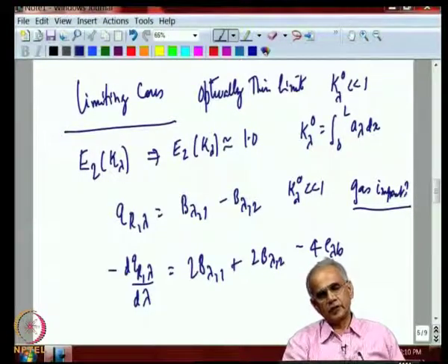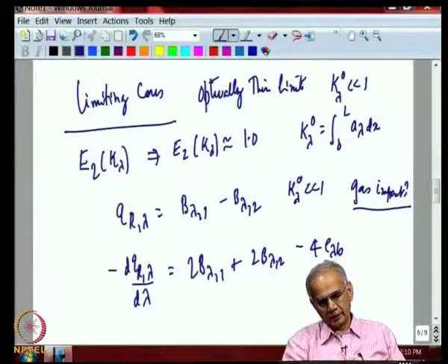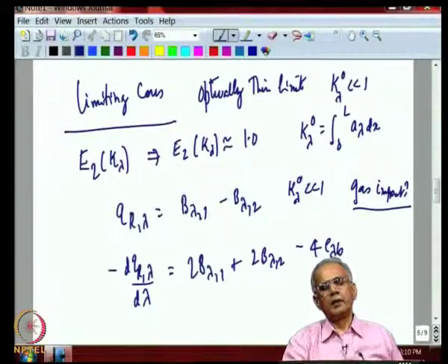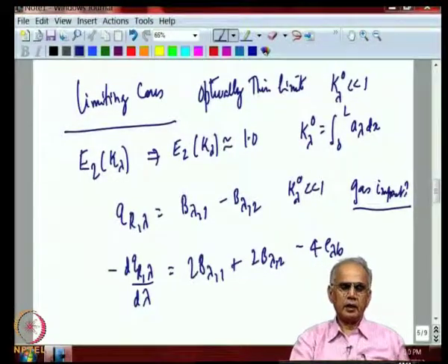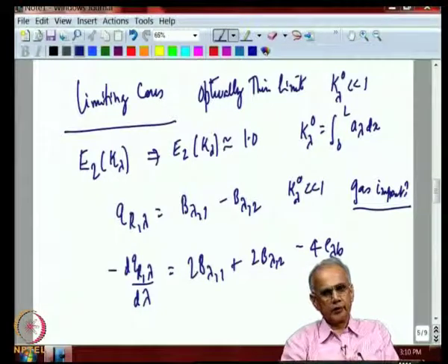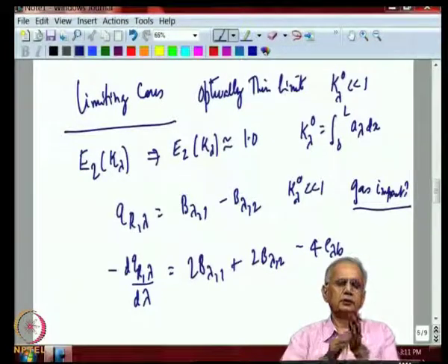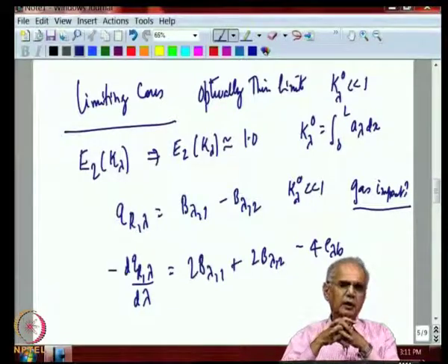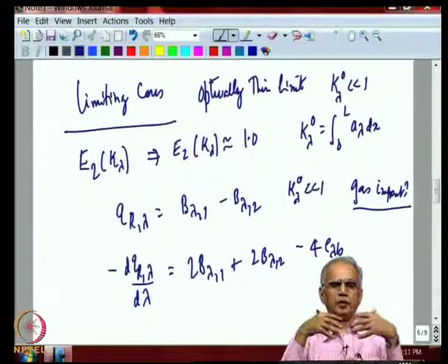So, as far as radiative fluxes in this enclosure are concerned, they are unaffected by the presence of the absorbing gas, but when it comes to the divergence of the flux, they are prominently there and they have to be accounted for. Now, this might puzzle some people as to how in the flux calculation you can neglect the role played by the gas, but in the divergence of the flux calculation, gas properties come into play in a prominent way.